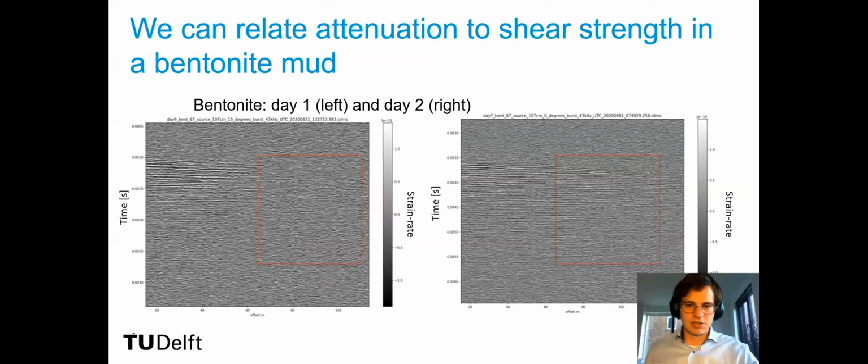we can very clearly identify 1, potentially 2 sources in the Sea Power wind farm, where this one is potentially an artifact, very clearly one turbine in the Rentel wind farm, and then as many as 4 or 6 turbines in the northern edge of the Rentel wind farm. And of course, the array resolution at these low frequencies means that differentiating these more clearly is probably impossible, but we'll continue to try.